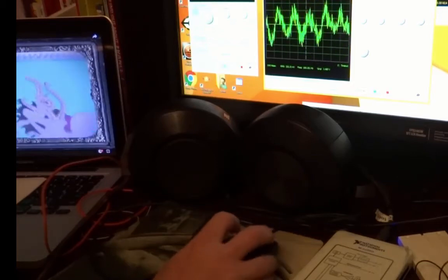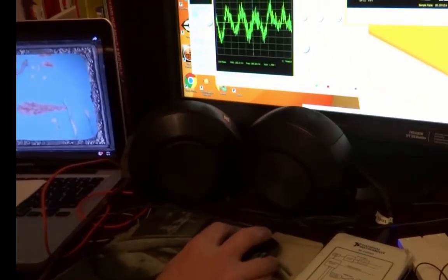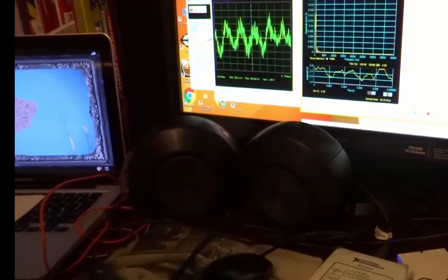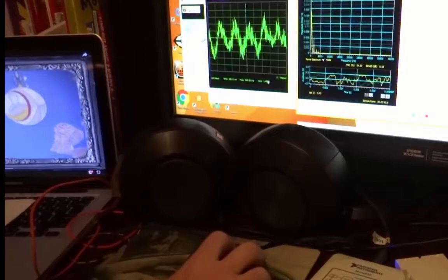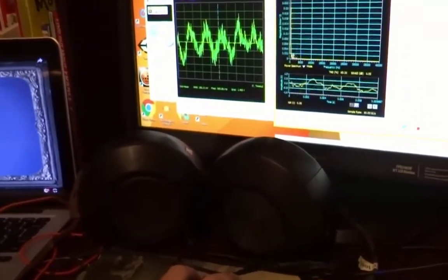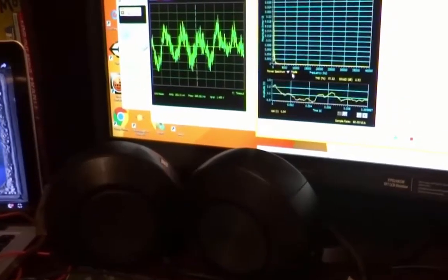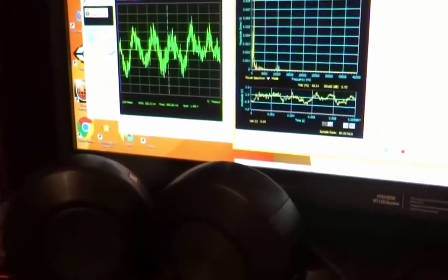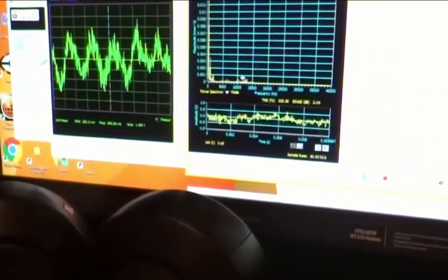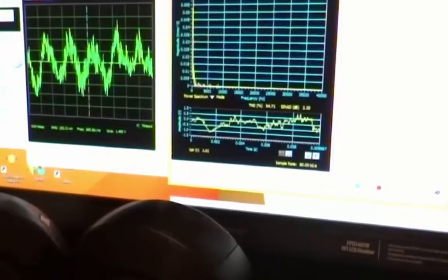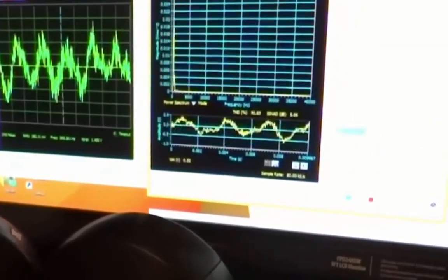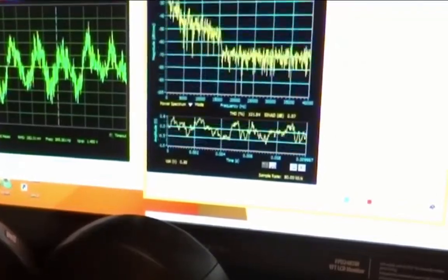So if I stop the scope, I can also move over to the dynamic spectrum analyzer and look at what this song looks like in the frequency domain. So most of it is living down here, below 500 hertz. There's a lot of details. There are details up here, for instance, cymbal hits and hi-hats in this higher frequency range. And really there's detail on a lot of the instruments that's up here that you may not be seeing on the scale.